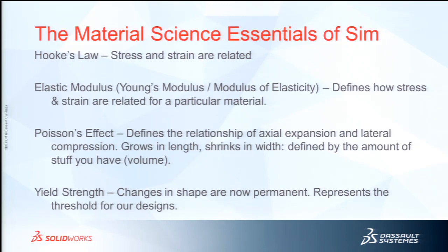And then your yield strength, you need to know that because that's the limit. That's the threshold that we're going to design to for our SOLIDWORKS designs, because after that, our changes are now permanent. So this is what we're going to design to.